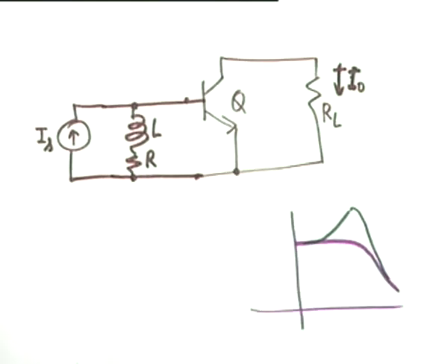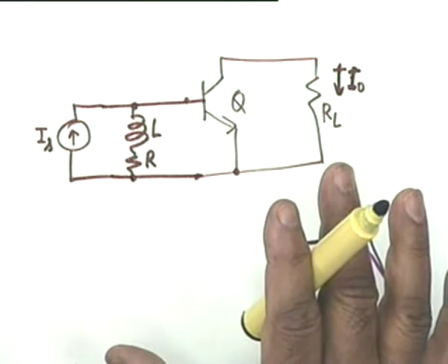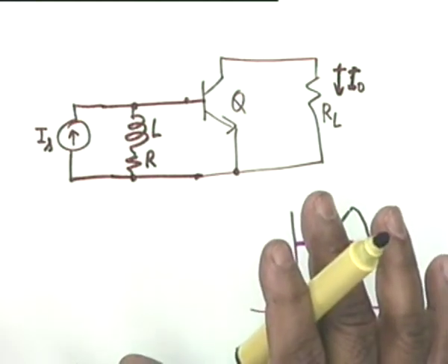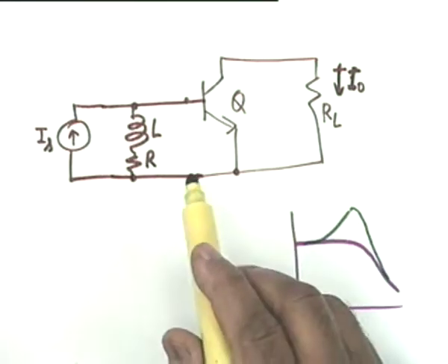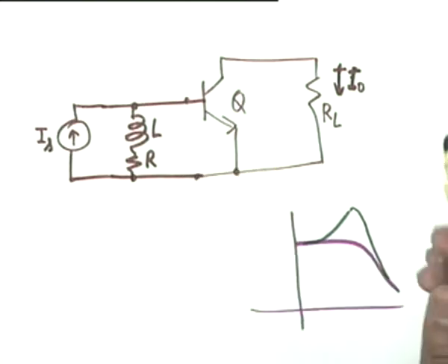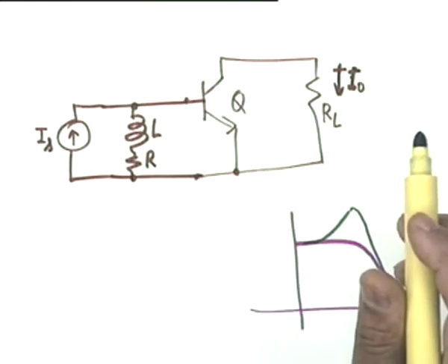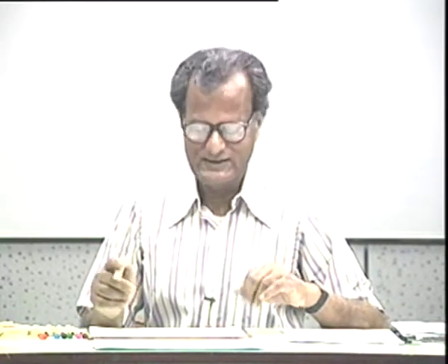We could also cancel some of the reactance by taking a series LR circuit, by making a series kind of resonance. Well, as we shall see through an example later, series resonance is less effective than parallel resonance. Usually series resonance is less effective than parallel. Well, it's not resonance. Let's call this a shunt peaking.